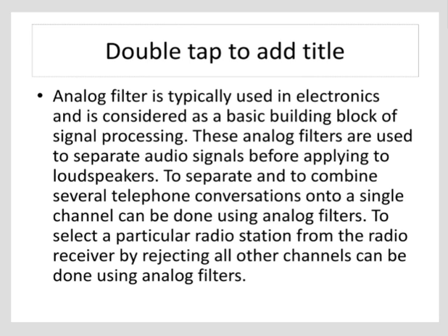Placing a digital filter in an analog signal chain would require the analog signal to be converted to a digital signal before the digital filtering could be applied, and with any conversion there are trade-offs in signal integrity. Digital filters work by oversampling and averaging and are programmable, but it is wise to apply an analog filter prior to the signal conversion.